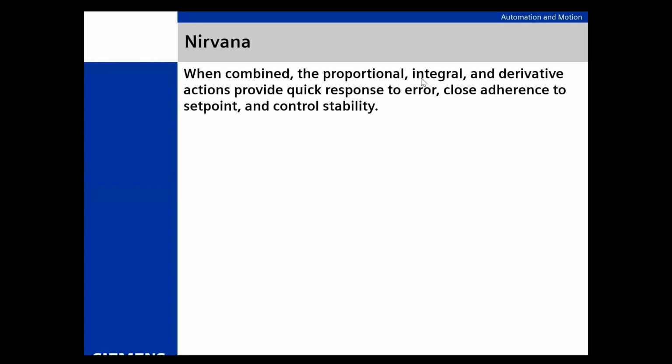The last one we have, it's more of a statement, but maybe you can elaborate. It states, huge challenge is getting operations to understand quarter wave tuning and process loop latency will rarely give them a flat line graph, especially with pH and conductivity in process streams.